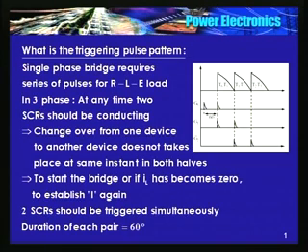Now 6 also may be triggered at the same instant, but then the moment you trigger 2, say after 120 degrees also, from here, 6 will turn off and 2 will come. So at any given instant, two devices should be triggered simultaneously.